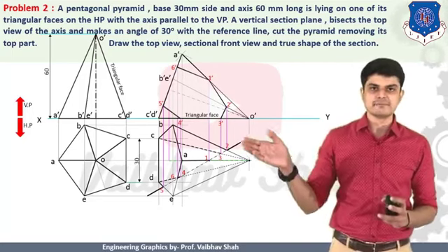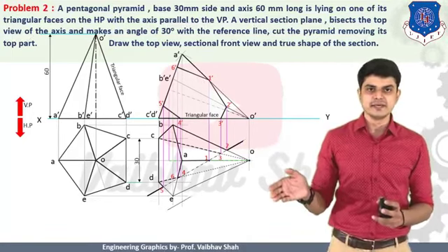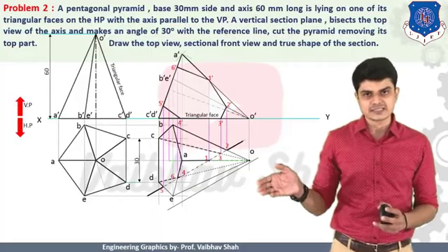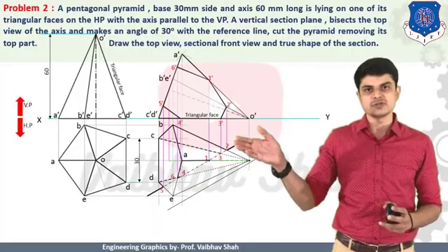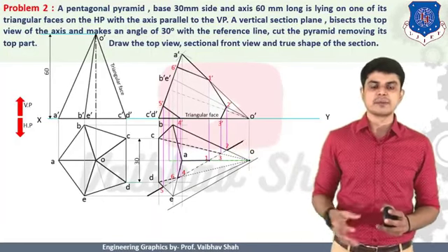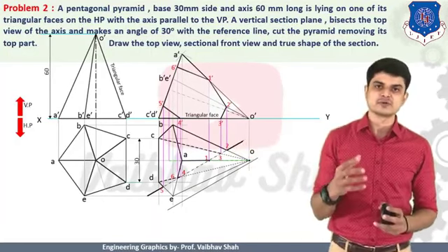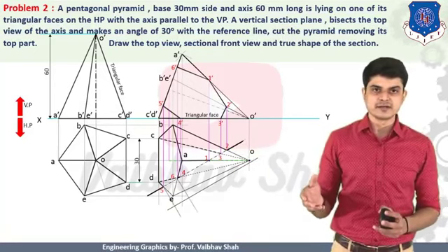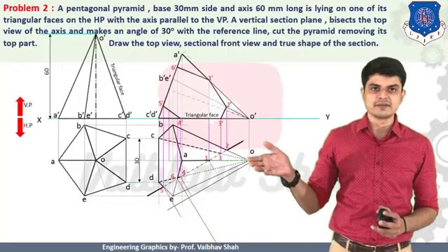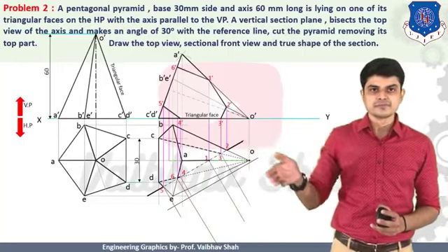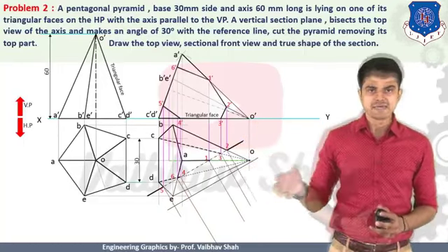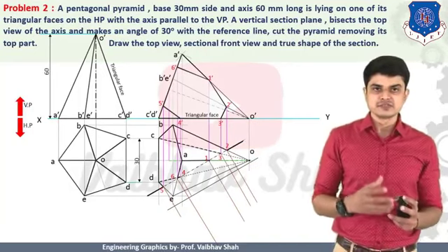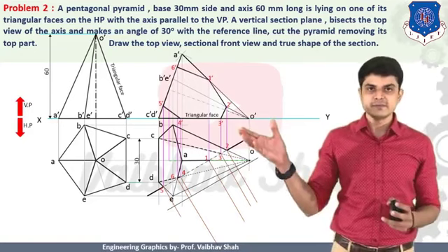So let us draw one line parallel to this line, and this will be your new line. So in place of drawing the perpendicular lines from your cutting plane, we are actually drawing one line parallel to the cutting plane line, and from that line we will try to generate perpendicular lines. So now what we need to do? Let us try to generate the perpendicular lines from each and every point of your cutting plane line like this. And now let us start the process. So let us first define the point 3 dash. So we know that point 3 dash.